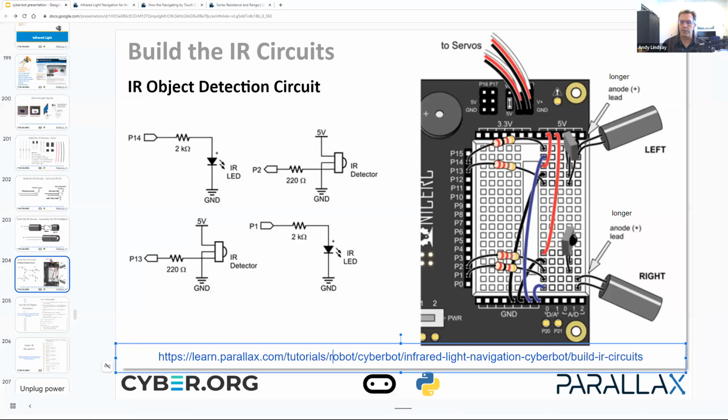Okay, so the first thing, can you change the IR to a different channel? I see each student controlling each. Okay, so that's somebody who has an infrared TV remote and they're trying to drive the robot around. And yes, the problem with that is that the students need to kind of stay away from each other. Otherwise, there will be crosstalk. And no, with most TV remotes, there is not a different channel.